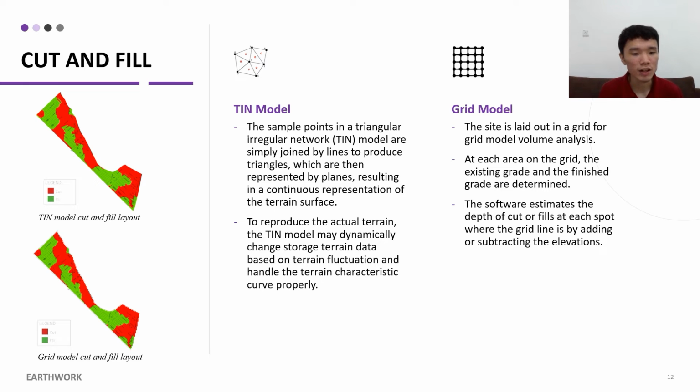Take the 3 sides of the initial triangle as the starting sides and use the empty outer criterion again to continue to find the next data point that meets the requirements. With this, we have found 3 other data points that fit our requirements. It should be noted in this process that the same site can only be used at most twice, otherwise the new triangle generated will be invalid. Repeat the steps of the second step until all the baselines are processed to form a complete triangle network. So far, the establishment of the TIN network has been completed.